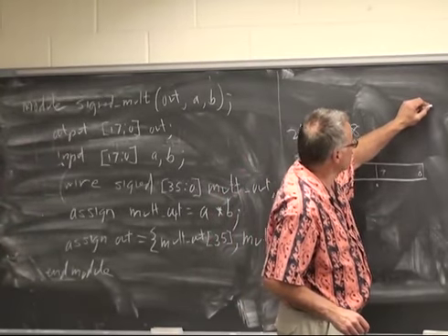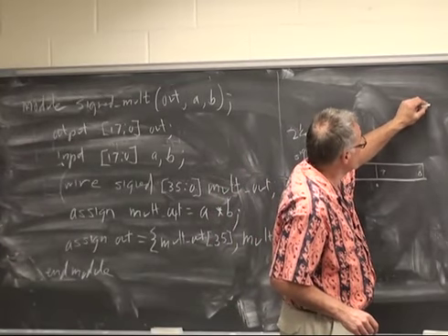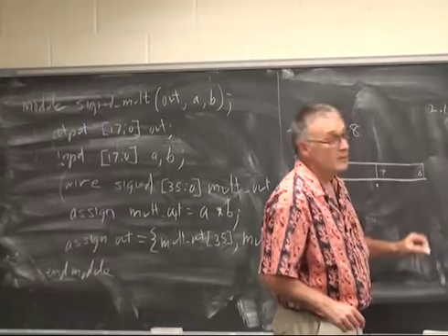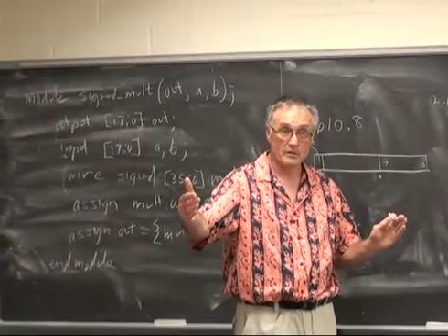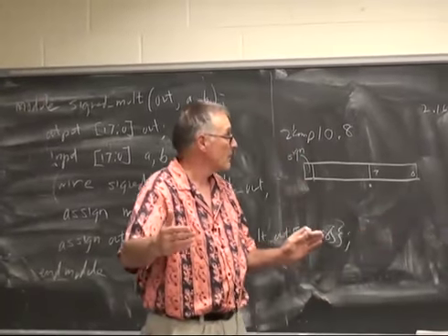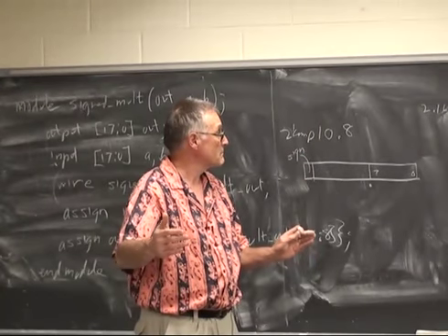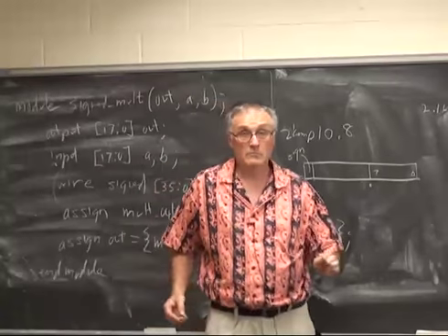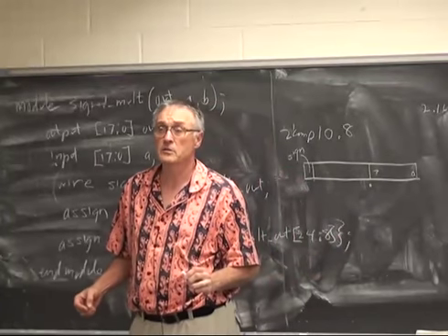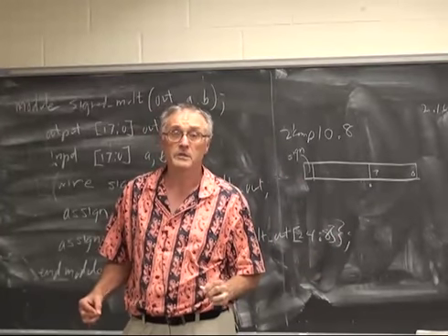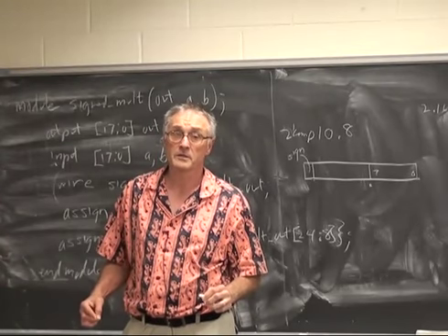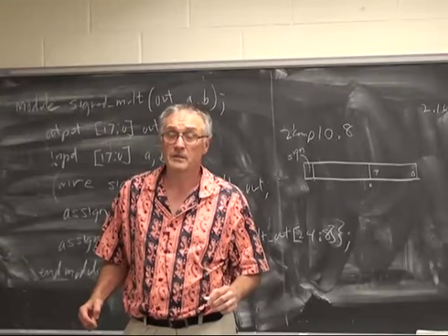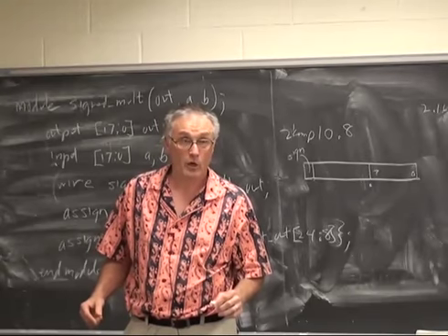So going to 2.16 might make a lot of sense, where you keep much more of the fraction. But you're going to have to make that decision depending on how much accuracy you think you need. And you'll be able to tell, because if you don't keep enough bits, the filters won't work.